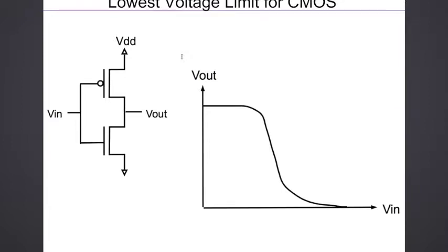And anytime you ask any such theory type question on digital circuits, first you want to have a simple circuit to use to understand and analyze that question. And the simplest circuit you can get is an inverter. And largely whatever works for inverters in some sense also works for other CMOS gates, because other CMOS gates are just a generalization of an inverter with a little bit more complexity in terms of the PMOS pull up and NMOS pull down stacks. So you look at first the inverter, right?